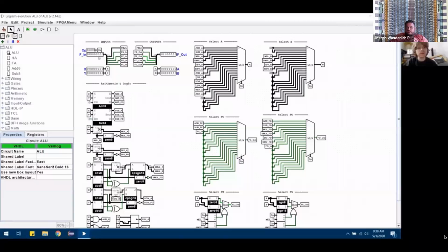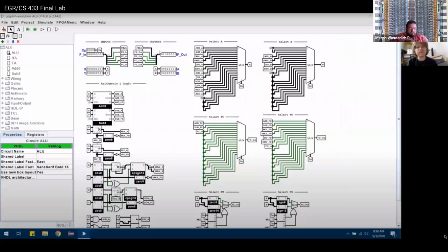It takes 2 inputs, X and Y, an opcode to select between the results, and the current flags register. We've only used the high 4 bits of the flags register, so we just pass on the first 4 bits as if nothing changed.